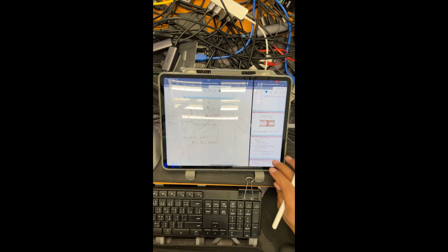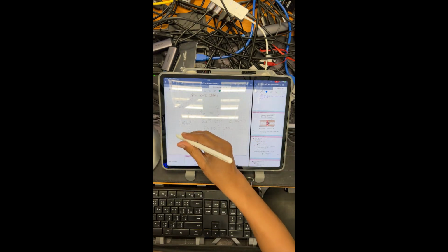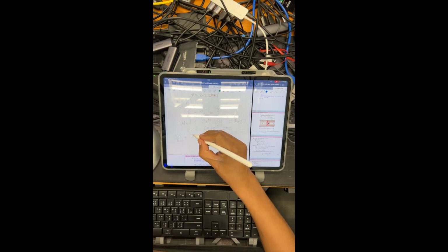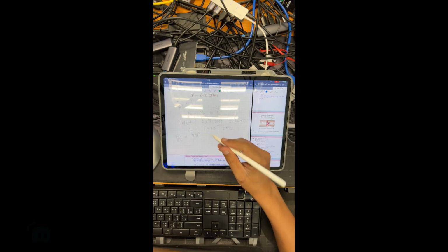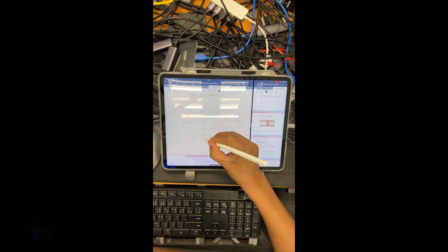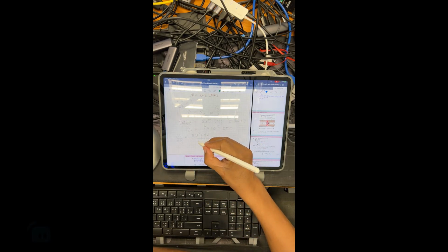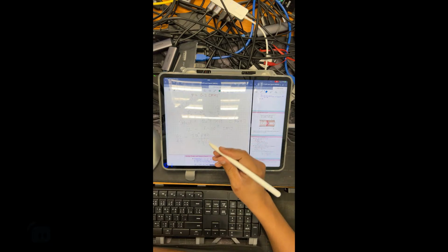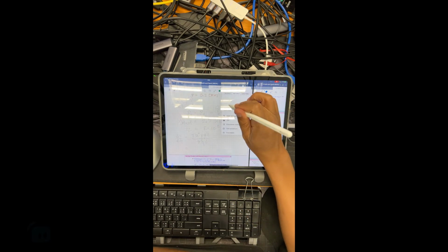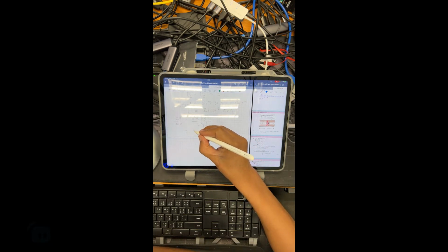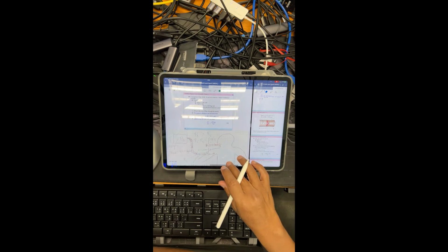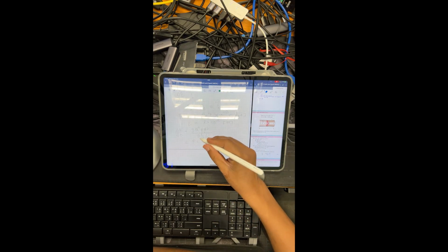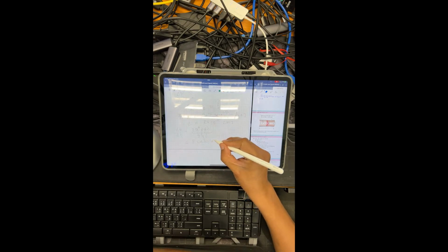All right, so let's go to the Poiseuille formula. Delta V by delta T is equal to pi R to the power of 4 times the pressure difference, rho g h, divided by 8 eta L, right? So now let's substitute everything into this. Pi is pi, and the radius R is 0.2 millimeter, or simply 0.2 times 10 to the negative 3 meter, right?